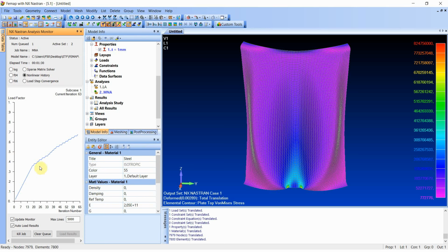And also, you cannot think about it as a stability plot, because here this is not a deformation, this is only iterations. So if more iterations are needed to obtain convergence, we can assume that this has something to do with plasticity, because it is harder to reach convergence then, and perhaps more iterations will be needed.